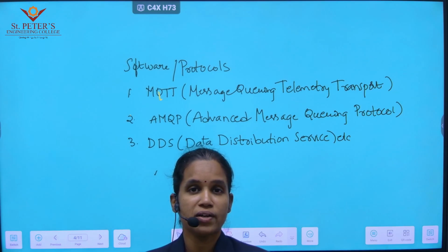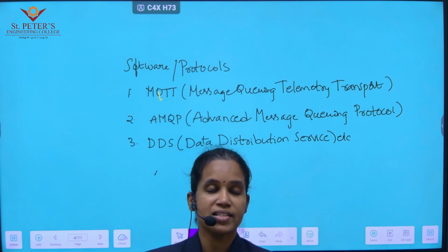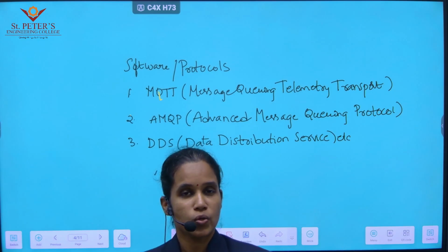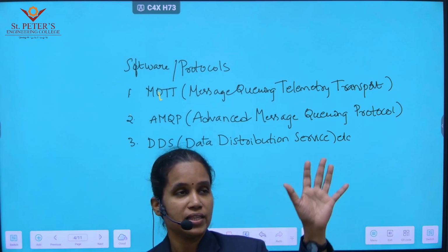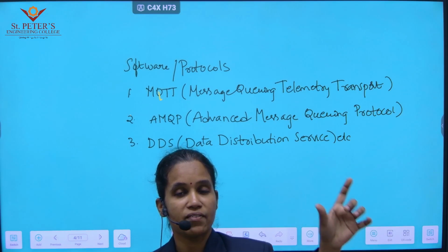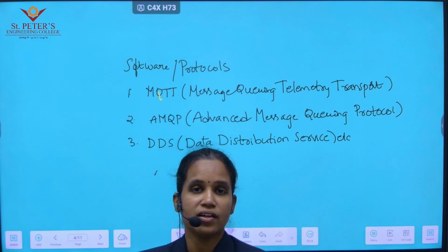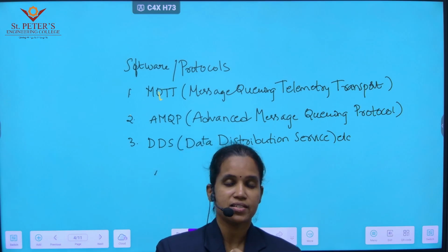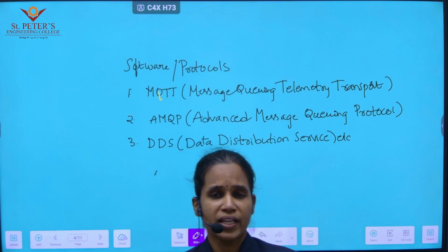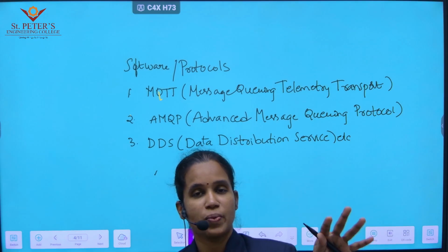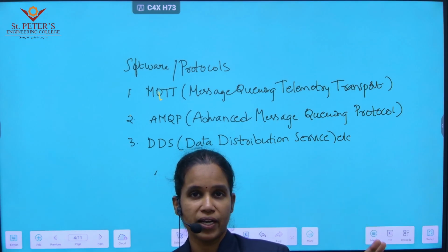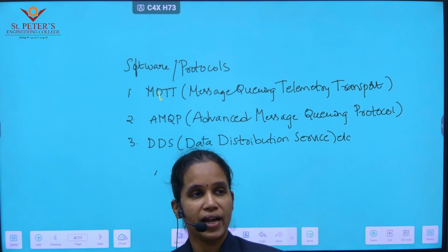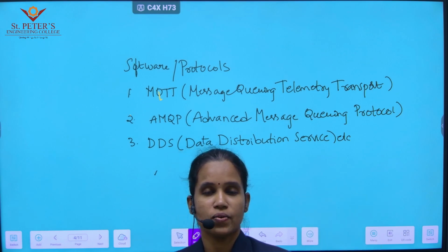So there is no need for me to again take a device and convert that Wi-Fi signal again into a Wi-Fi signal. So immediately I'll pair up the two smart devices which are having the Wi-Fi module directly with the router. I hope you understood the difference. So in the first case, those two smart devices are using non-IP technologies. So using an Amazon Alexa app, I paired it up and I converted those non-IP signals into IP signals.